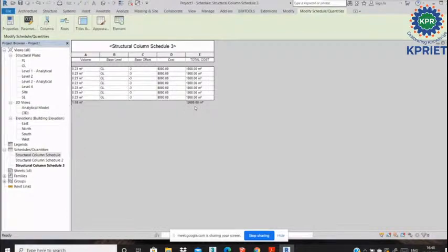Understand how to take the amount of your concrete columns? Simply go to volume. You go to 0.23 meter, simply click this 0.23 meter. Directly our cost is 8,000 per meter cube. Simply enter this, and automatically it will be calculated. You see, automatically 12,600 for your 7 columns amount and 1.5 meter cube volume for all 7 columns.